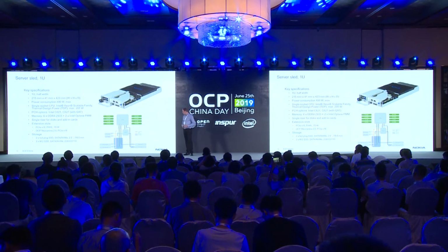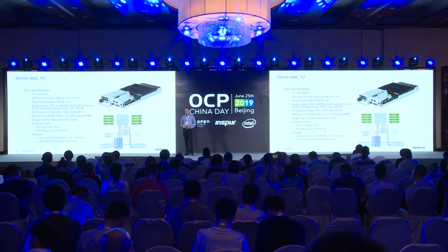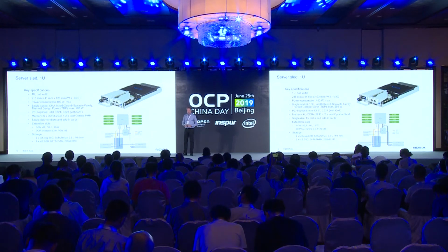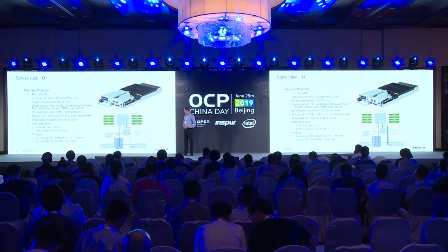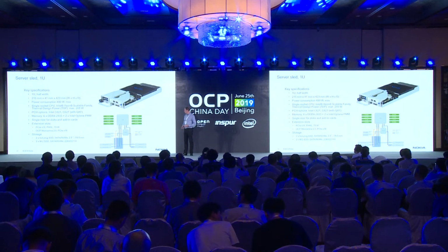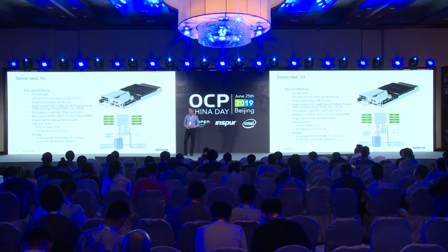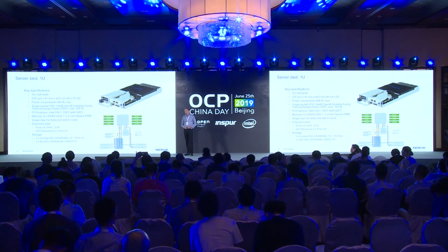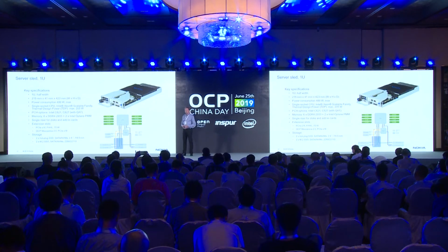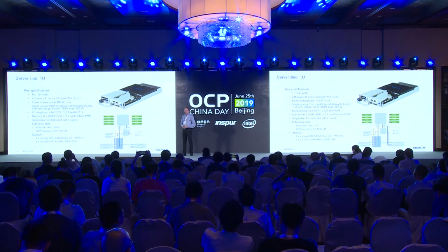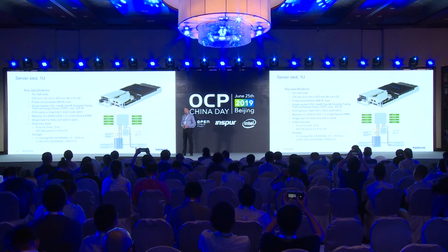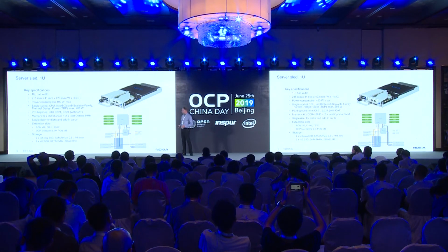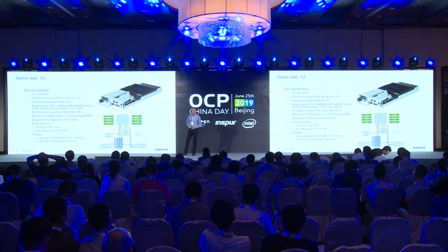Okay, here you can see the block diagram of the 1U sled. Maybe worth mentioning is that in this design we have one common riser card that is supporting the SSDs and the PCIe I/O options. Using that riser, we can redefine the PCIe connectivity inside the server when needed.